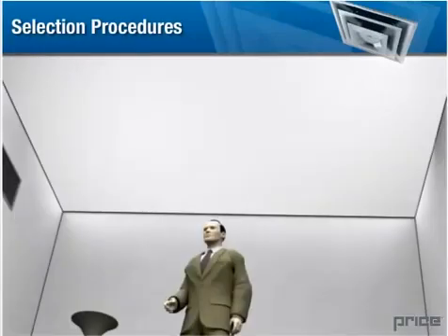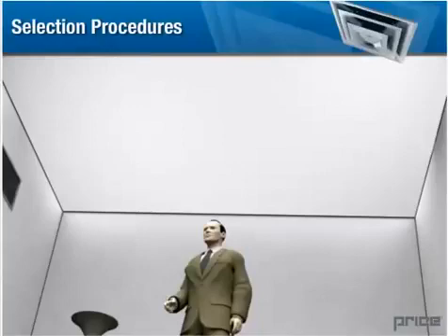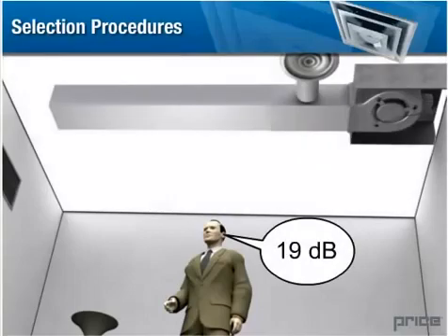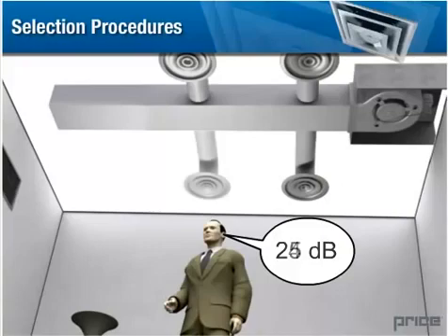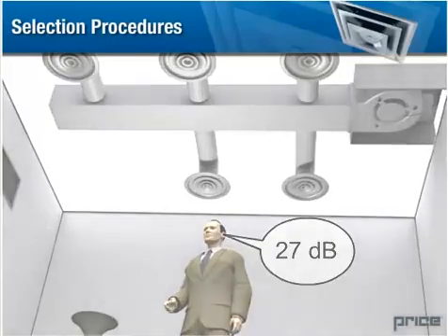For a large area with a large number of outlets, consider an area of 400 to 600 square feet as the maximum area where more than one outlet will contribute to the overall noise level. Take the area to be square or of an aspect ratio of 1 to 2. By using an overlay on the diffuser layout, the maximum concentration of diffusers can be determined, and thus the overall noise level can be calculated. The above procedure is a simple and fast method of adding multiple air outlets which will provide reasonable accuracy.